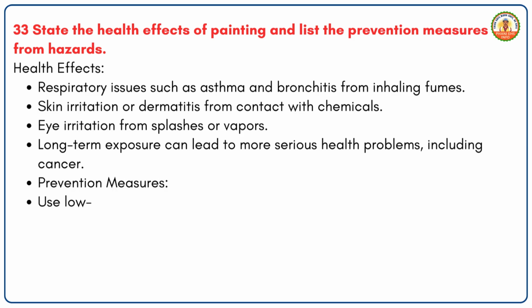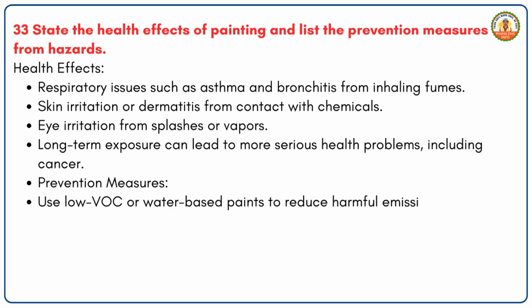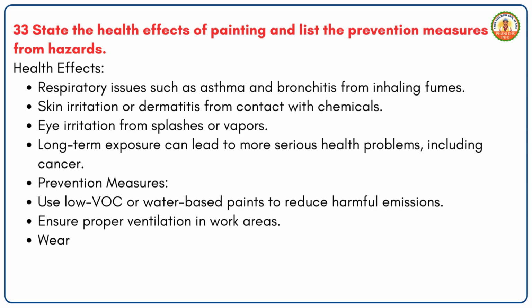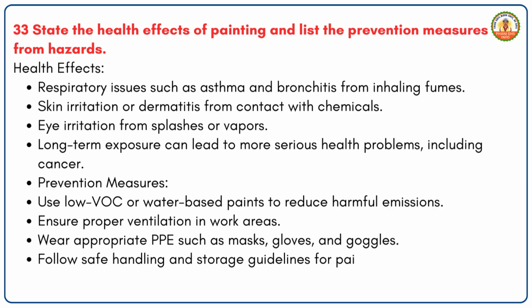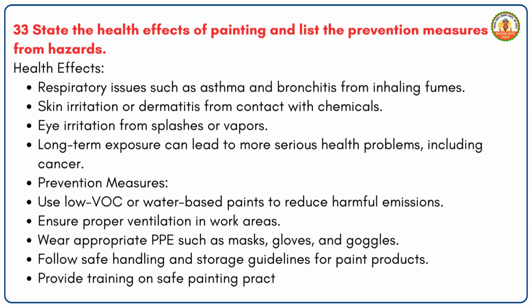Prevention measures. Use low-VOC or water-based paints to reduce harmful emissions. Ensure proper ventilation in work areas. Wear appropriate PPE such as masks, gloves, and goggles. Follow safe handling and storage guidelines for paint products. Provide training on safe painting practices and emergency procedures.